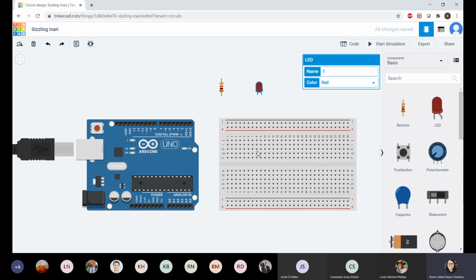For these electrical components, if you click on top of that, you will see that in vertical, they are all connected. So if you connect something here, let's say you put a battery with 5 volts, that means that all this line is going to have 5 volts. But notice that it's just up to here, and this other side is not energized. On the other hand, if you connect here in this corner, it will energize all in vertical.